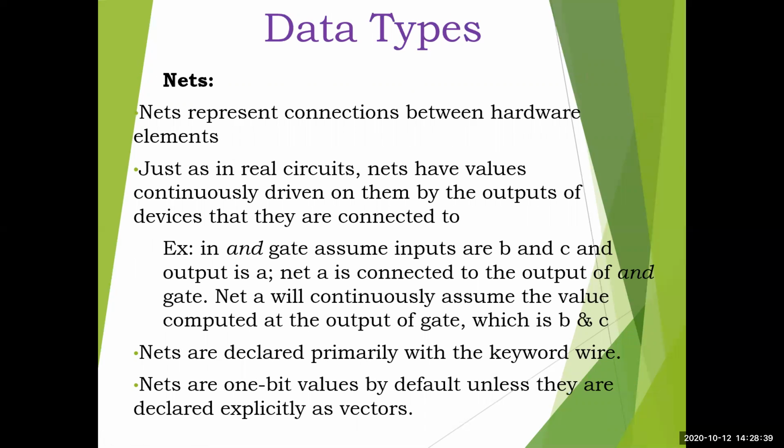So nets represent connections between hardware elements. Just as in real circuits, nets have values continuously driven on them by the outputs of devices that they are connected to. For example, you have an AND gate, right? How do we represent an AND gate?